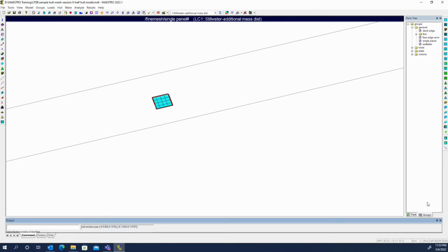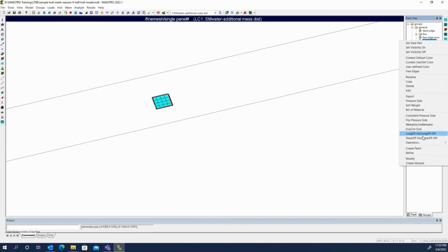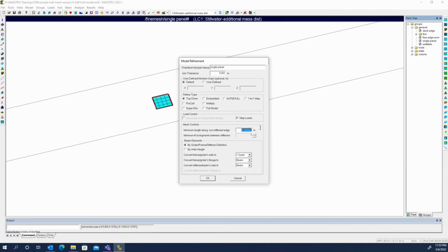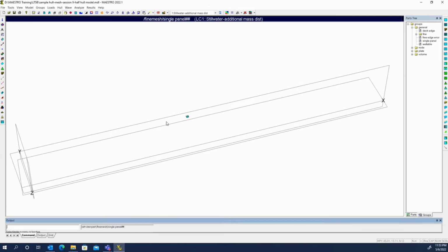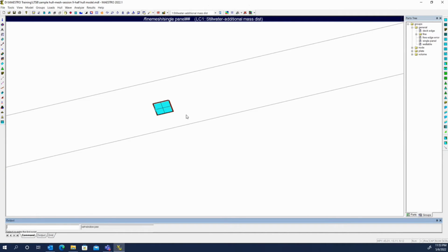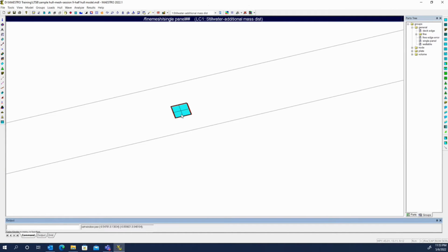And if we use something that doesn't divide exactly in there, such as, let's say, 4, we get a 2 by 2. Now we would still get the 2 by 2 if we use 0.5, but there should have been 2.5 in here, which obviously isn't an option. So it uses the two whole elements and just increases the size to fit the edge.